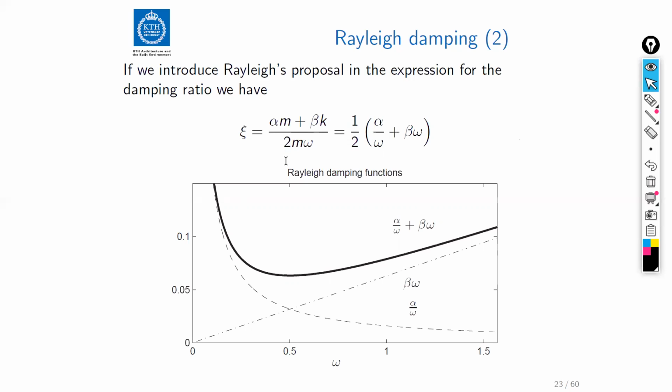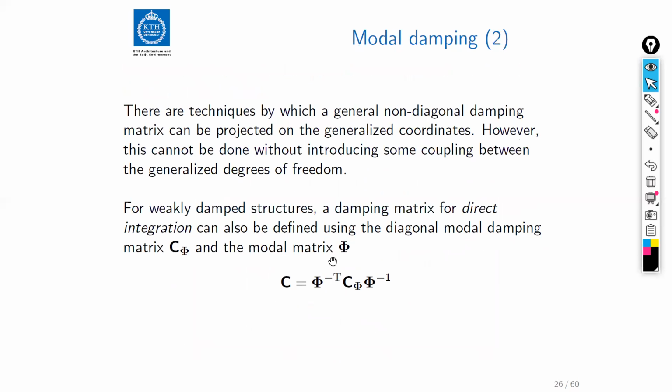But nevertheless, it's really difficult to get one that gives you precisely the same damping ratio on all modes of vibration. So this idea here is to use the modal matrix and assign in the modal domain the specific values at each mode of vibration that you want, and then transform this back to the physical domain and use that as a normal viscous damping matrix.